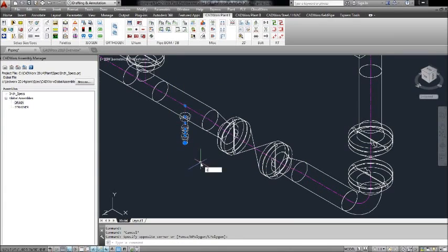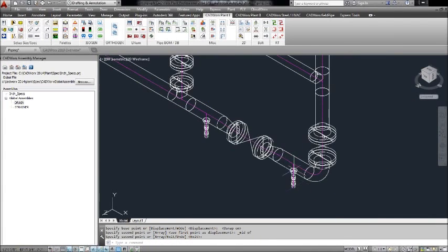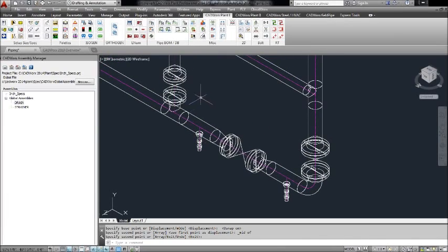Now once I have that set up there, I can use AutoCAD to do some moving around. I can copy this over here and put it on the midpoint on this side because it's the same nominal size. So the assemblies, just because you created it as an assembly, you don't need to necessarily insert it as an assembly every time. We insert it once for each nominal and spec, and then you can use AutoCAD to copy them around. And because these are set up as global assemblies, these assemblies will be available to me regardless of what project I'm working on, regardless of what PRJ I have loaded for specifications.